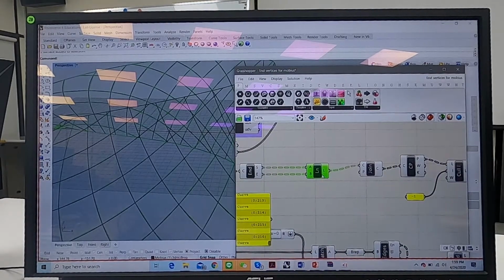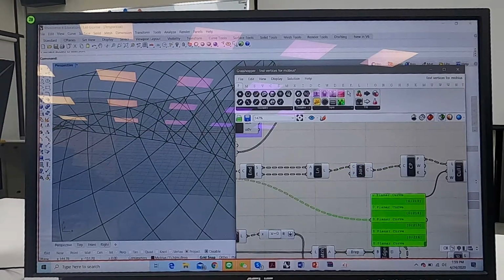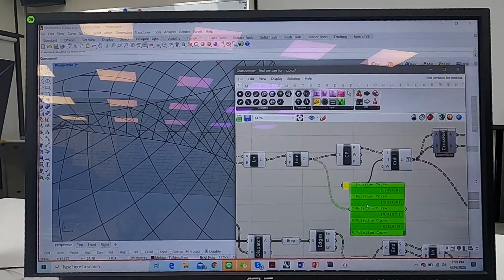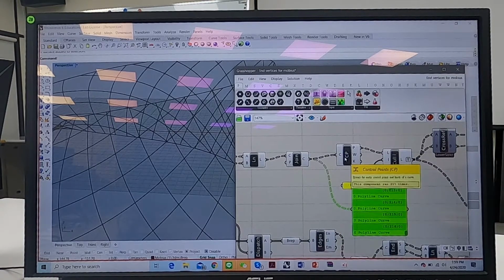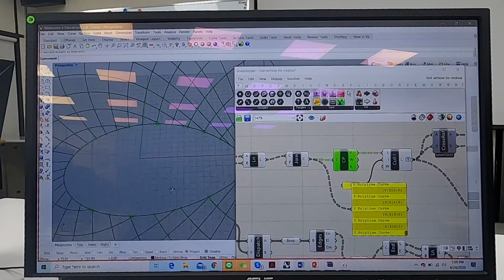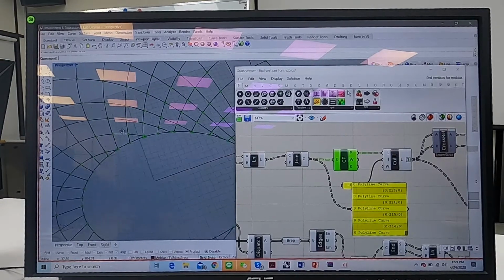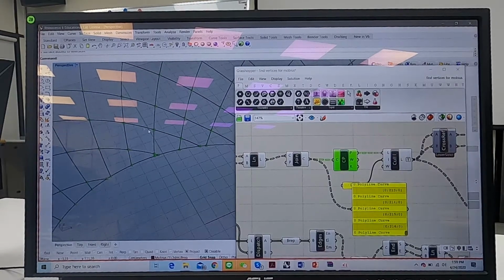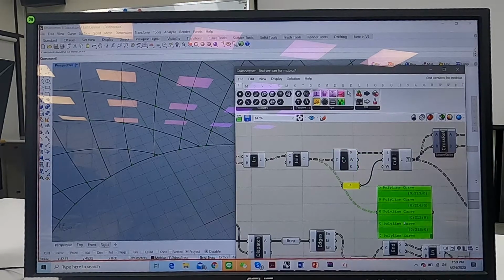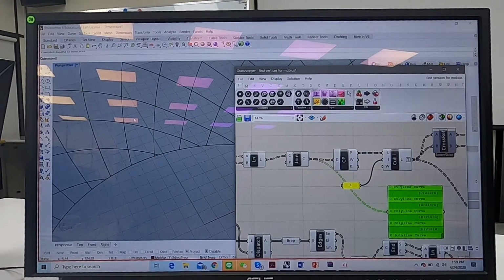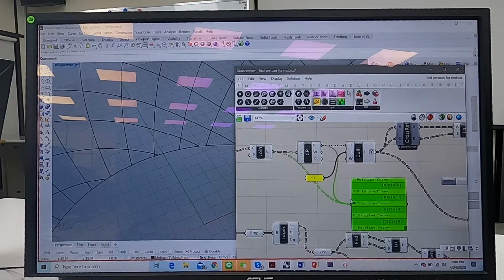And we join them into a single polyline for each panel. Find the control points of them. Because we want to make sure that the order is correct, for each of these quadrangles you find 5 points, because it repeats the first point.